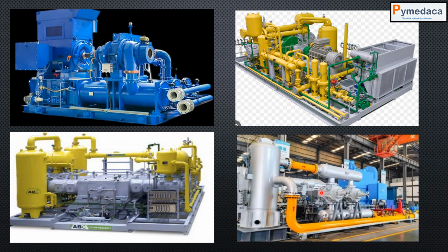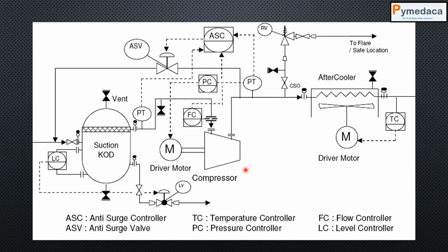There are different types of compressors, but one of the important things about compressors is that based on the type of compressor, there will be different piping requirements. However, these requirements are addressed in the P&ID. Okay, you will have to follow the P&ID. You will have to find the nozzles of the compressors. You will have to find the interconnections actually. So all these things can be followed with respect to the P&ID. But when it comes to the location of the compressors, then you will have to do some work. That work you will be coordinating with the respective technical safety engineer in order to locate it.